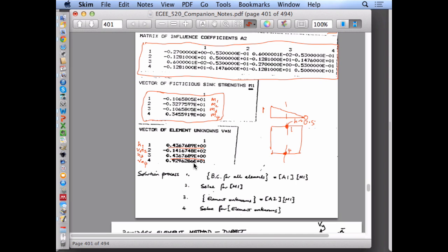Almost. And the velocity across here should be from high head to low head. We've used Darcy's law already. Hydraulic conductivity, dH dx. I think the hydraulic conductivity I used is clearly not 1. I think it's 10, just from looking at these.